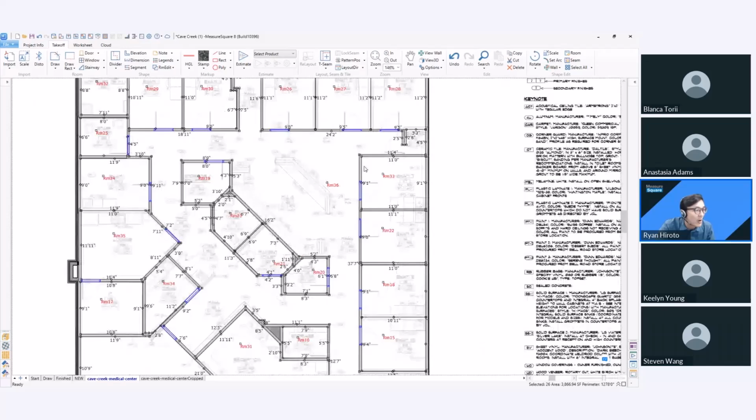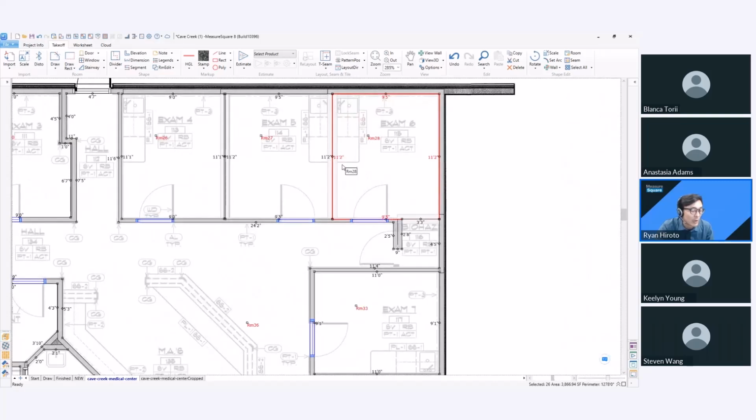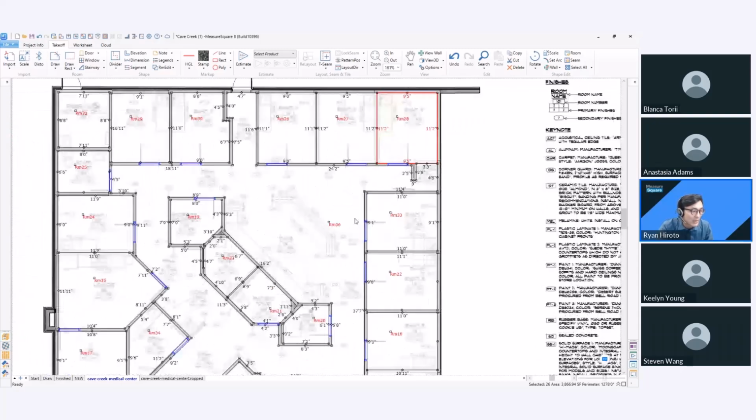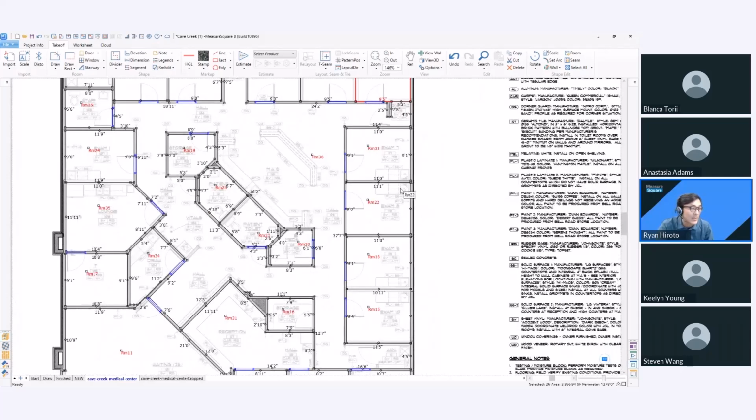But sometimes, because of the line detail, and all architectural drawings are different, guys, when you get a plan, it's just not going to be well suited for the auto takeoff. Just for your own confidence, you may want to still draw out the rooms, because you can verify quality by drawing it yourself and it doesn't add too much extra time. However, if you come into a project that's pretty simple and you can quickly check, or it's a quick turn project, it's definitely something that you can play with.